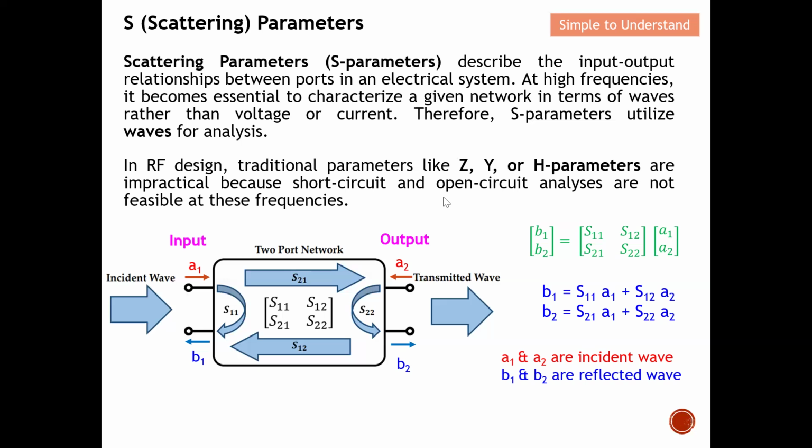Same for this open circuit analysis. Let's take the capacitor. If you still remember, the reactance of the capacitor is equal to 1 over 2 pi FC. So from here you can see that at a very small frequency, when you do 1 divided by 2 pi F, the small number, you actually have a very big reactance. So I can still have an open circuit. However, when the frequency keeps on increasing, the 1 divided by the number becomes a very significant number, and hence I cannot use a capacitor as an open circuit anymore.